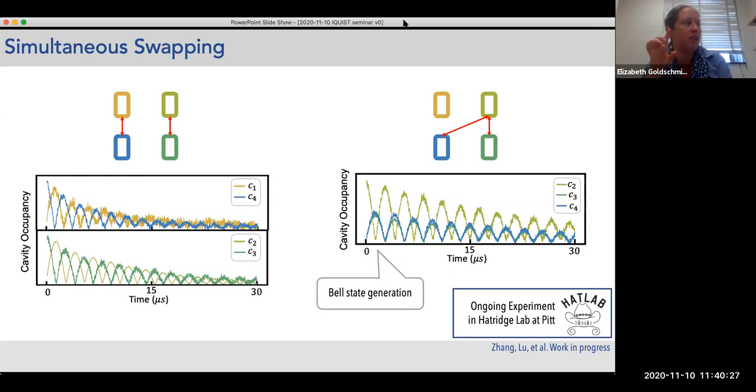Then the question is, is the decay intrinsic due to losses in the walls, or is it due to coupling out of the cavity to the transmission line? This is a coupling part, actually. In this case, this has to do with how this was measured. And this is also very much related to what Paul is asking. Because the measurement is not of population, but of field, you would need to square this to get the sinusoidal one. And to Jim's question, the fact that what's been measured here is the microwave photons being emitted from the cavities is a part of the measurement scheme. It makes it really easy to analyze this experiment. So it's overcoupled in this case. It's a compromise between measurability and Q factors, basically.